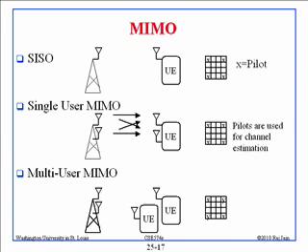And they have to be, by the way, quarter wavelength or half wavelength apart. And at 700 megahertz, the wavelength is so big that you would need to carry an antenna with you, like an umbrella or something. So that doesn't work, right? So then they invented what we call multi-user MIMO, where you need 2 antennas, but they don't have to be on the same equipment. They could be on 2 different users.